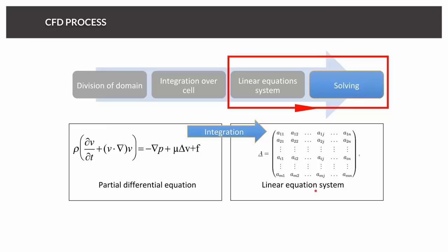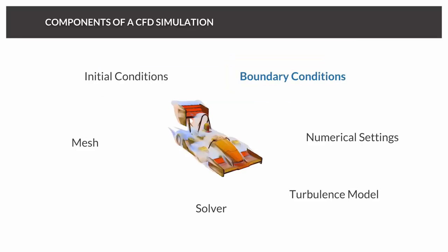Therefore, usually what we do is we initialize everything with 0 except for the velocity and pressure, which are initialized using a potential flow approach. But this is something we'll also talk about more next week. But remember, initial values, every time you do this for CFD, for Racecar, use potential flow to initialize.